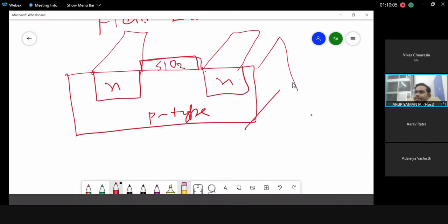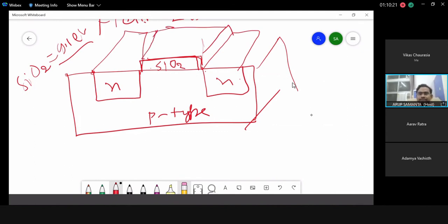It is a semiconductor band gap insulator. This SiO2 band gap, I wrote, is 9.1 electron volts, a huge band gap. So no transport of electrons is possible because of this insulator. On top of that, this is the insulating part which should run along this direction. So this is pre-made SiO2, and then you put some metal on top of that. This is the metal oxide semiconductor. That's why it's called metal oxide semiconductor.